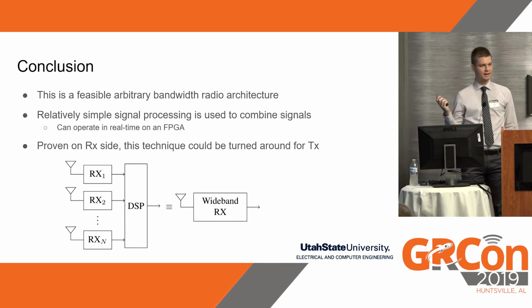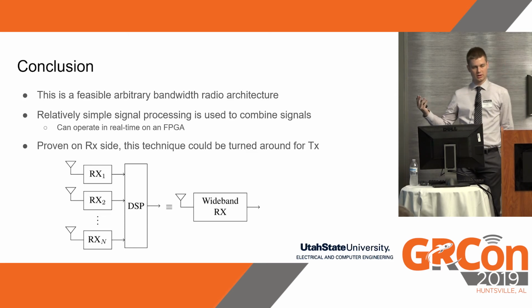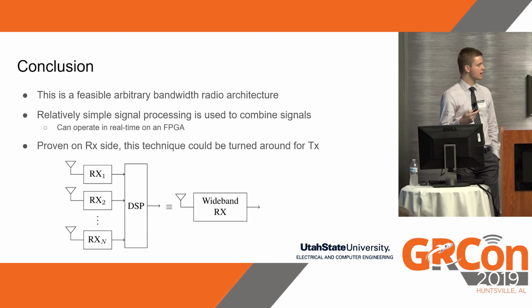So we proved this on the RX side. On the TX side, it's essentially the same thing. One nice feature of the 9361s is there's an internal loopback that you can enable so that when you're transmitting, you can receive on one of the receive channels the same signal you're transmitting, and you could use that to synchronize the signals in the exact same way.